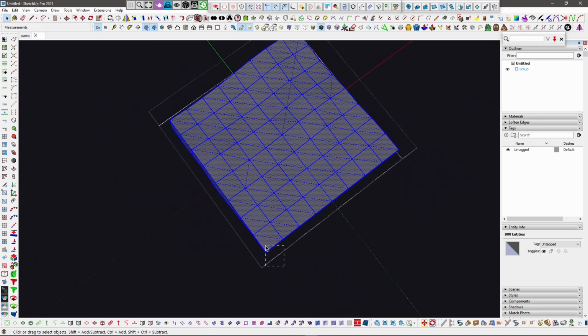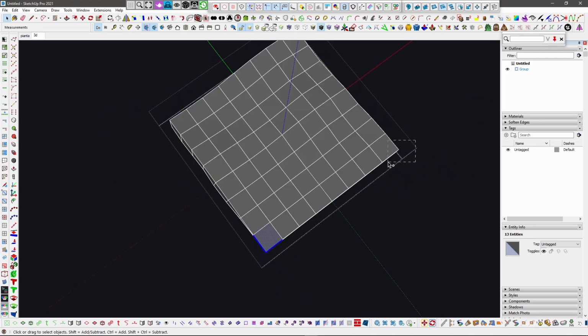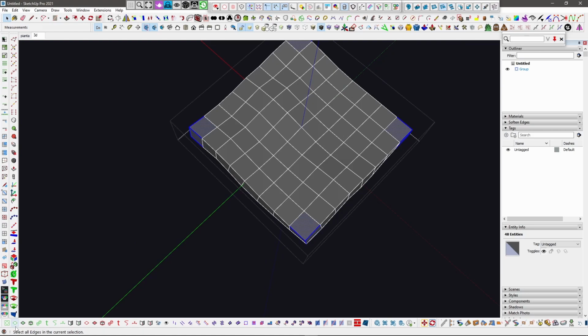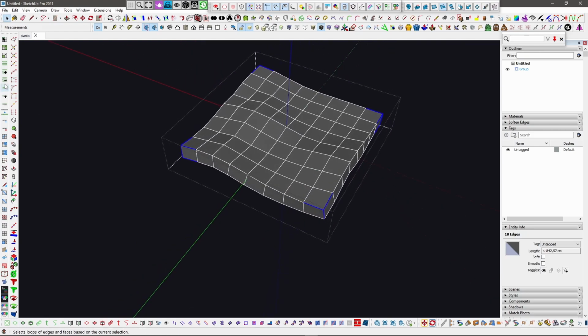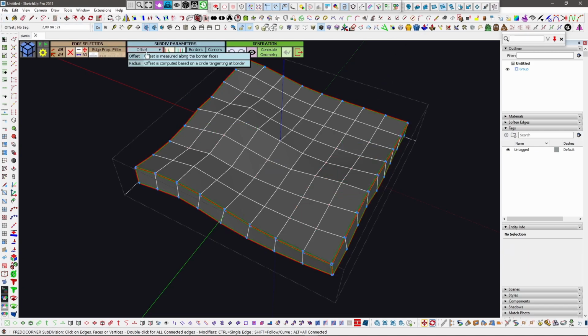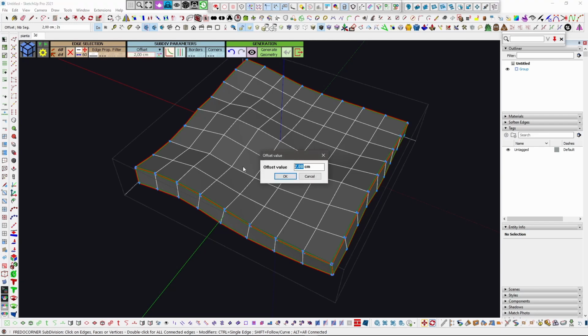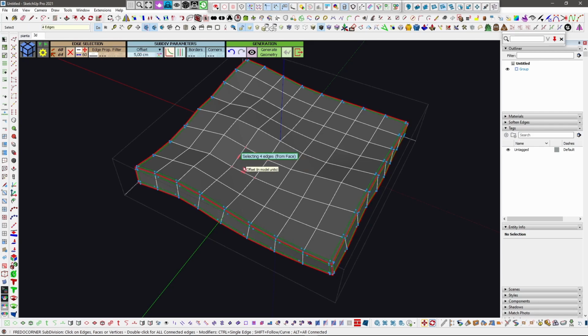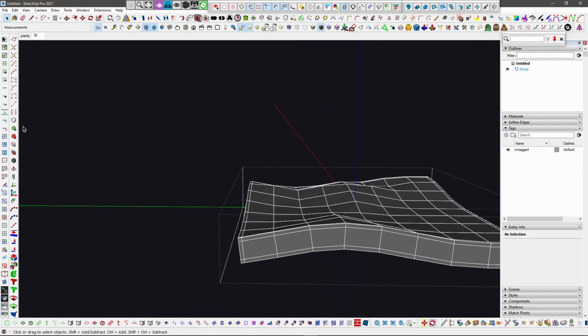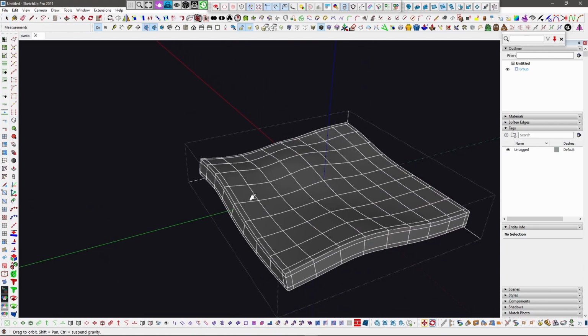Then let's say I want to select my corners here and here too, and filter my edges and loop this, and add some chamfer for subdivision with the Fredo corner, maybe 3 centimeters, also 5. Something smooth, but not too much smooth. Let's see how this subdivides, and that's fine.